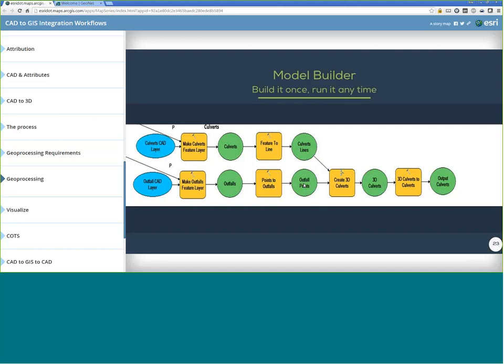So I tell it what the input CAD file points and lines are, and then it runs through this process. Now, the one thing you're not seeing is that there's about 40 other layers in here that use the same process. So it just runs through each of the different layers: center lines, culverts, topography, the contours, the telco, all the telco nodes, all the street control points. All of those different layers contribute to this final output file geodatabase.